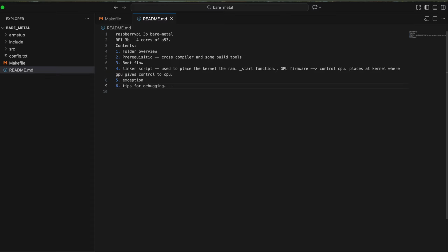And here I will mostly give debugging tips based on UART prints. We can have multiple ways to debug, like a debugger and all, but those systems are very costly. So we can use UART. UART is the best and the cheapest way to debug.